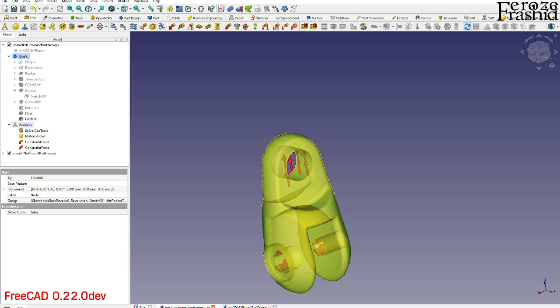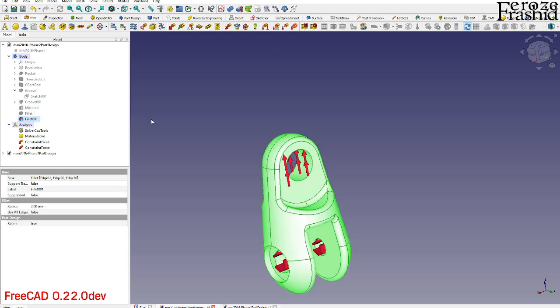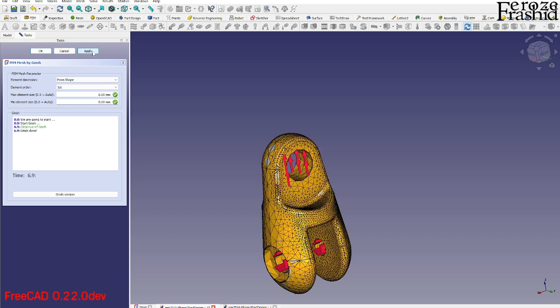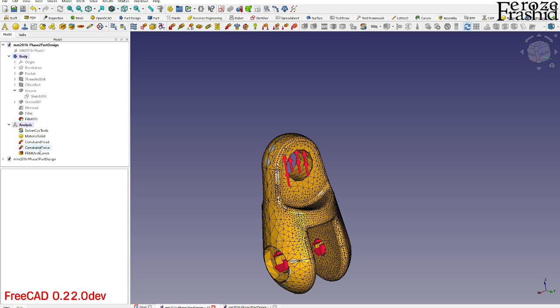So we can add the whole mesh or the fillet. So I'm gonna go ahead and select the fillet, add gmesh. I'm gonna say first order and keep it automatic. Hit apply, see how it plays out. It played out good. So we are looking at 6 point, this end value, gmesh done in black, no red. Okay, we have everything.